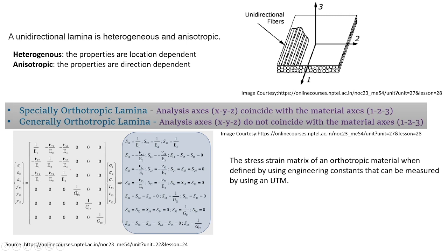But for an orthotropic material lamina, when we consider only two directions and treat the third direction as having very less width, we reduce the whole stress-strain matrix into terms of only stress and strain in directions one and two, considering this third direction as very less, so we don't take properties in that direction.